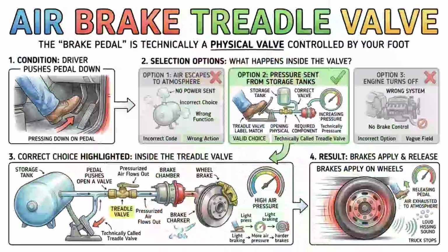You might wonder why heavy commercial vehicles use air brakes instead of the hydraulic fluid brakes found in passenger cars. The primary reason is that compressed air is incredibly reliable and completely safe for stopping massive amounts of weight over long distances. If a hydraulic brake line breaks in your car, you lose all your braking fluid and your ability to stop completely. With an air brake system, even if you develop a small leak, the system can continually pump more air, and it has built-in mechanical fail-safes to stop the truck if all air is lost.